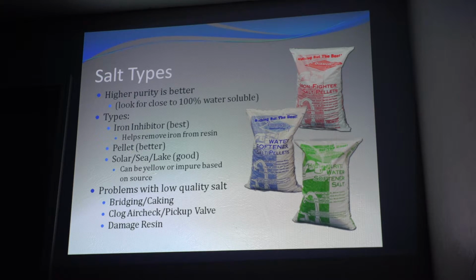The type of salt that's going to hurt resin, and it's not even mentioned on here, is block salt. I had somebody come in the other day who still uses block. I hadn't heard that for years. Yep. And if you ever open up a brine tank where there's block in it, you'll see almost a foamy scum floating on top of the water.